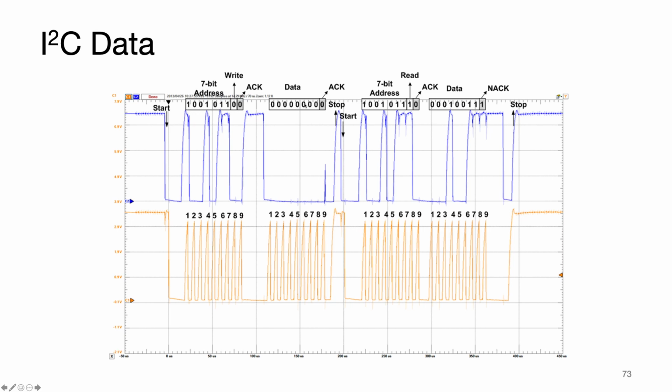Next, what do we write in there? All zeros. Big whoop. Okay, all zeros went in, but the peripheral still ACKed. Okay, got it. You see the stop bit occurs, so clock went high, stop went on. Now we restart the next round. Start goes low, then clock goes low.